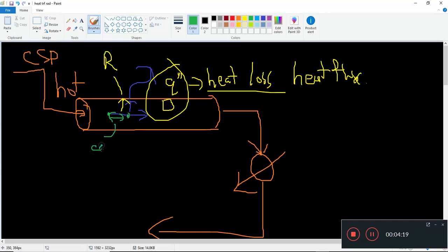Again, there will be convection, conduction, and radiation affecting heat transfer between two points in the fluid, and that we also want to take into account. How do we begin to calculate this? We need to consider something called divergence of heat flux.